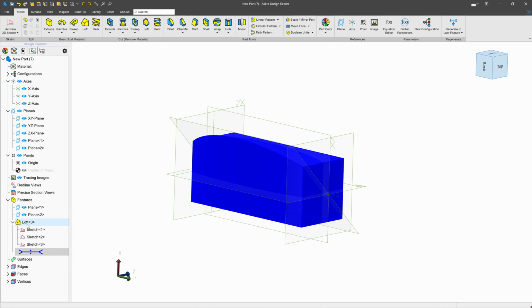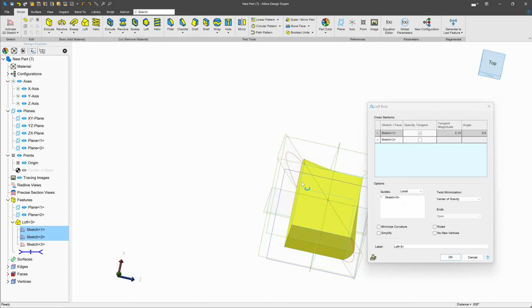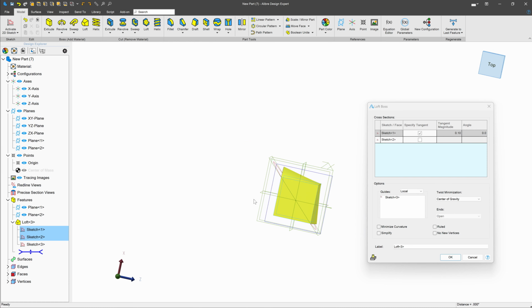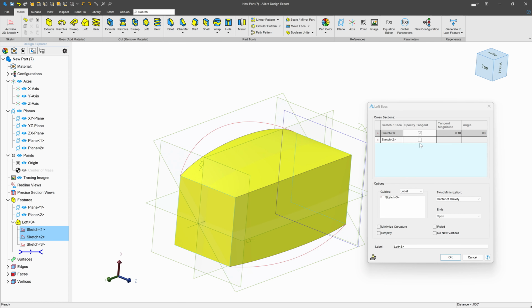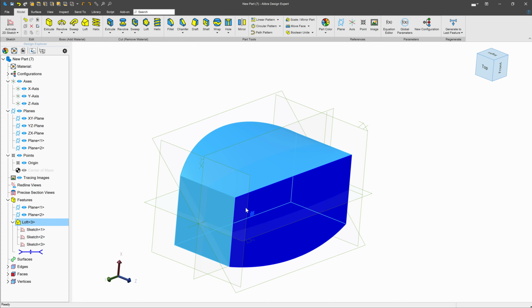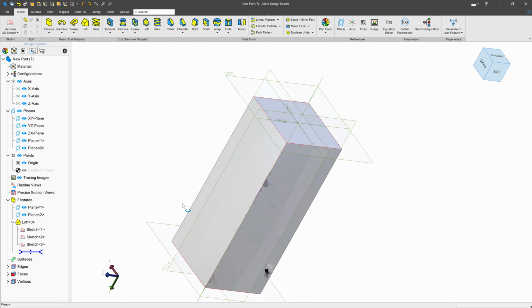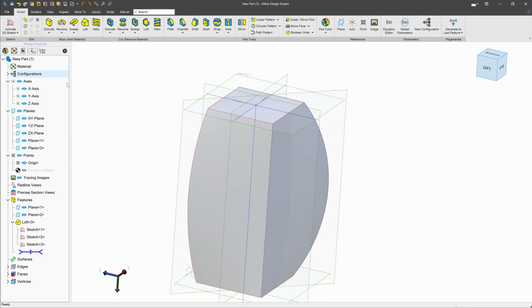And you'll notice also when using these guide curves, tangent magnitudes don't apply very much. They do a little bit, but you can play with it. But sometimes your tangent magnitudes just aren't really applicable. So it's kind of one or the other, but you can play with it and see what you like. So that is how we handle global and local guide curves when we loft.